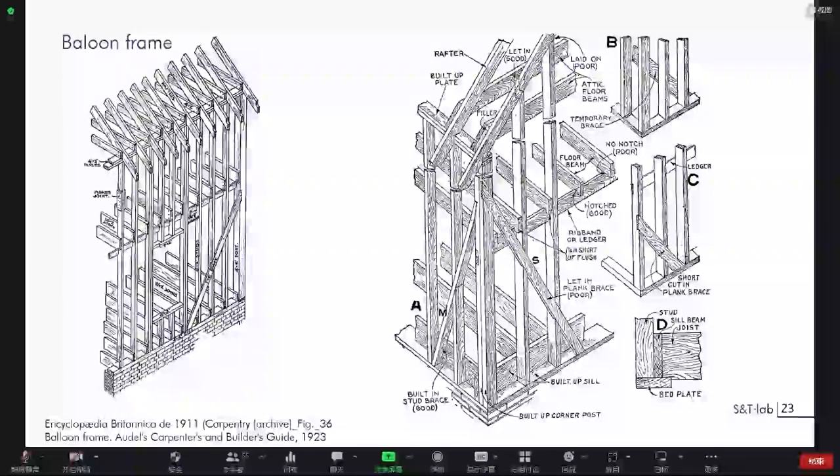And a question of bracing that will be managed with some diagonals here, but most of the time you can also use the cladding with an angle of close to 45-60 degrees to develop bracing.